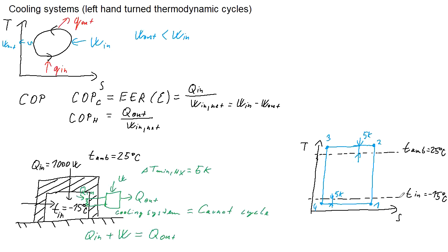So just to make sure, this is the temperature inside of the box, from which we need to transfer the heat to the working fluid, so that the working fluid can get rid of the heat, plus the energy from the compressor work also as heat, so it will need to reject it into the environment, and the heat will flow this way. This is heat out, this is heat in. Now let's move the axis a little bit lower.